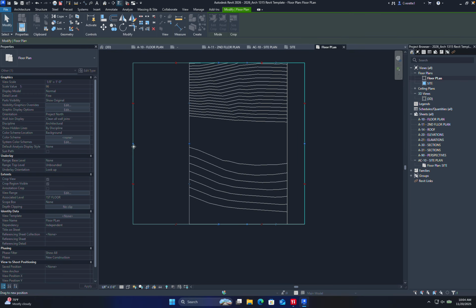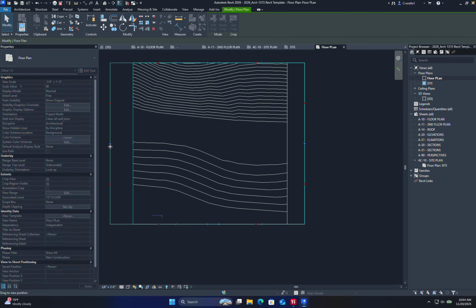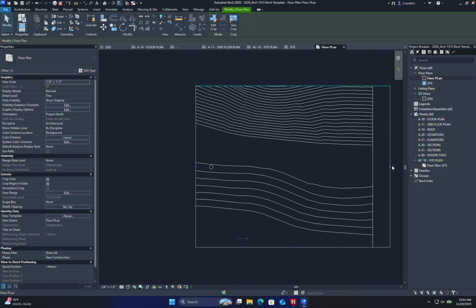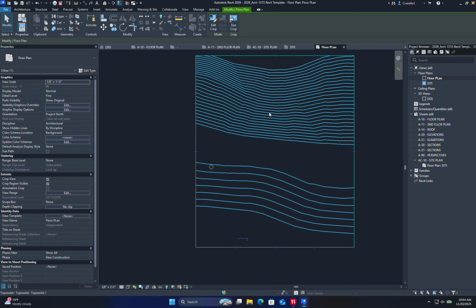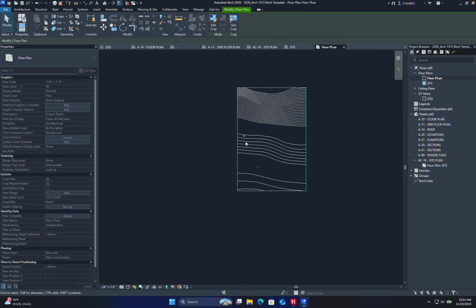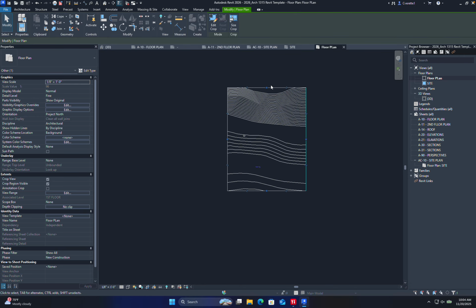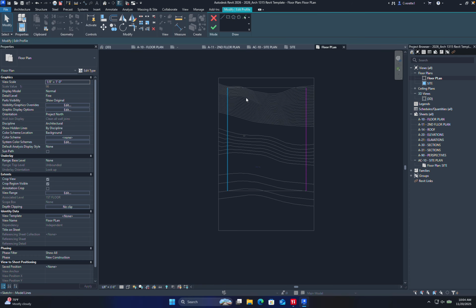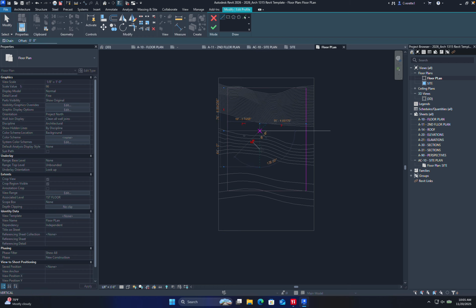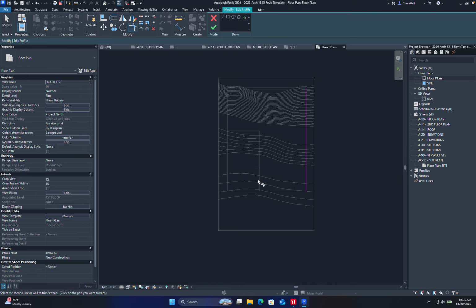That way, of course, I can figure out where to put my building. I'm going to go probably towards the middle. By default, this can take some time. What is nice about it though is I can double click on it and actually control it as well. If I wanted something really funky for studio, I can use TR for trim. I click on the two that I want to keep, and I can trim very differently in Revit.